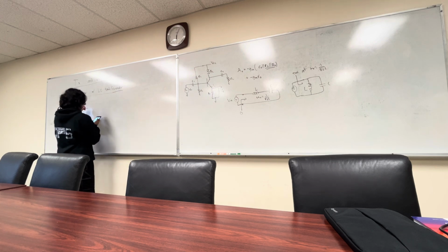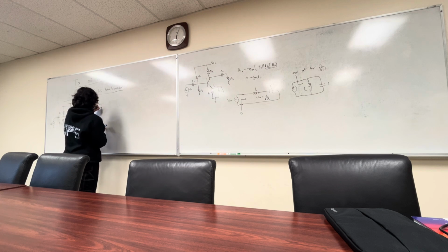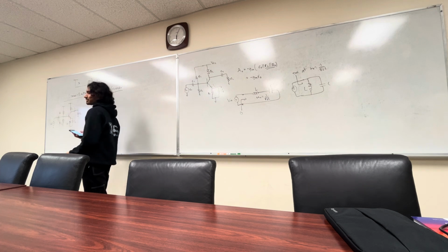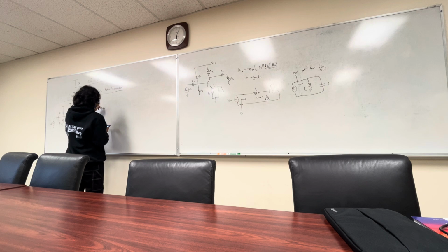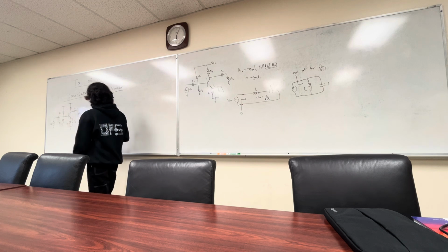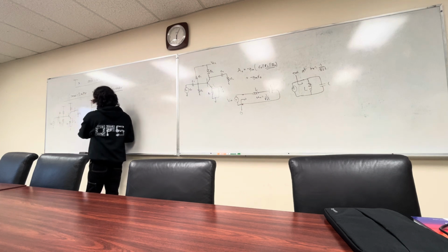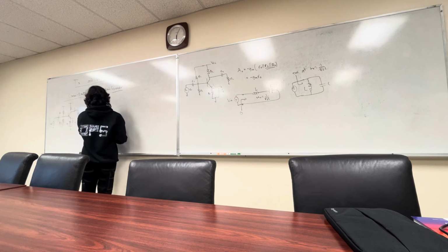So we do this, and this is something that I think everyone takes for granted when making the small signal model, but these resistors are still there in a small signal model. We just assume them to be so large that we don't see them. And sometimes they do come into play. Very rarely, but we do care about it nonetheless. We're going to assume that at this frequency of interest we're doing a small signal model at, CE is bypassed, in which case the emitter looks like it's being tied directly to ground. Like that.